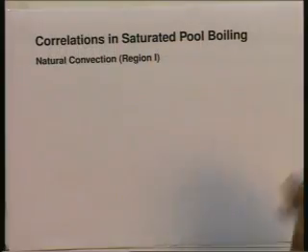Now, in region 1, I have mentioned it, but let me repeat, change of phase does not occur at the heated surface. That is the point which I made to you last time. The heated surface is at the bottom, and the change of phase does not occur there. What happens is, because of the small temperature difference, the liquid gets slightly superheated, maybe by a degree, 2 degrees or something like that.